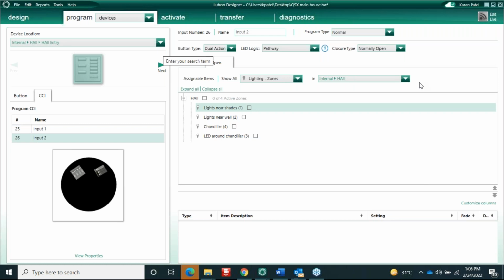In case I have the panels installed with those light control modules, in the future the client requests some fans to be turned on and off during the scene. Can I have the fans, like the bathroom fans, open or close with the scene? Is it a contact closure fan, or a high voltage fan?